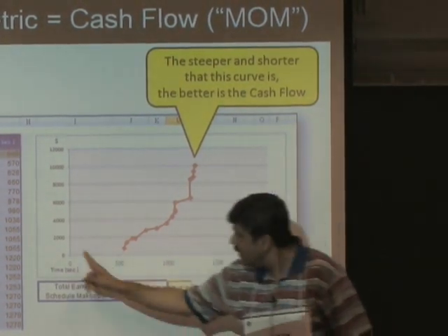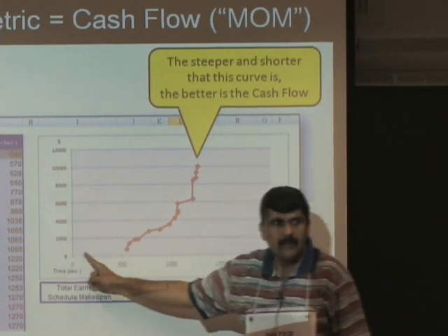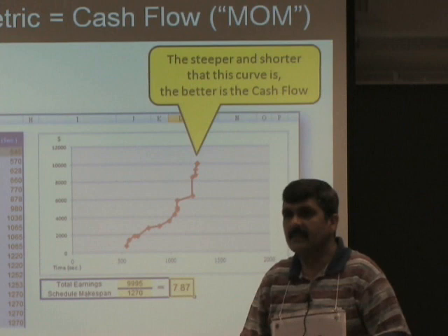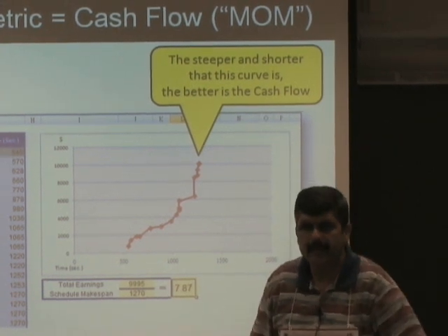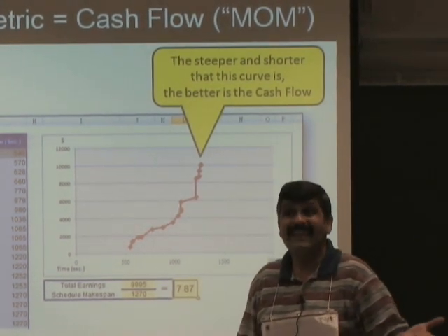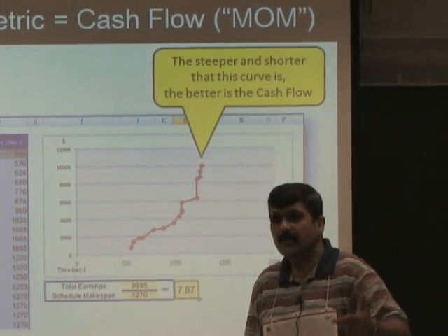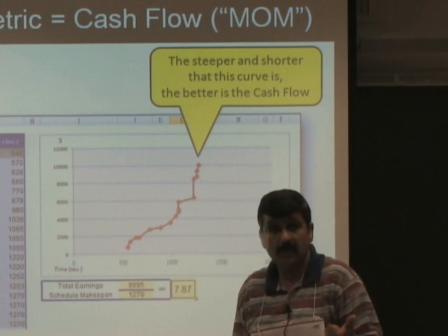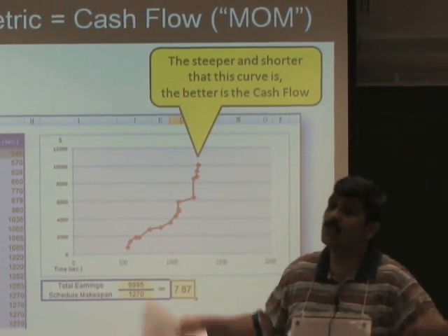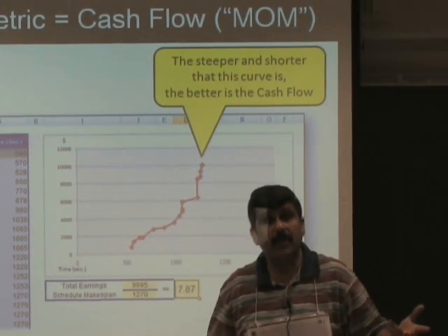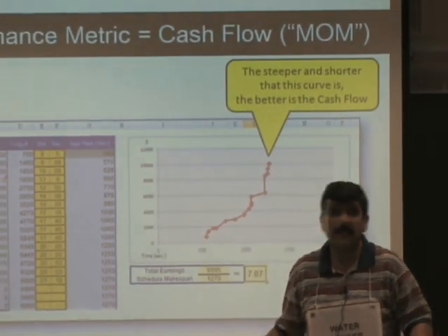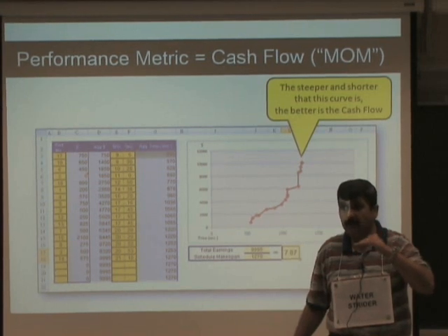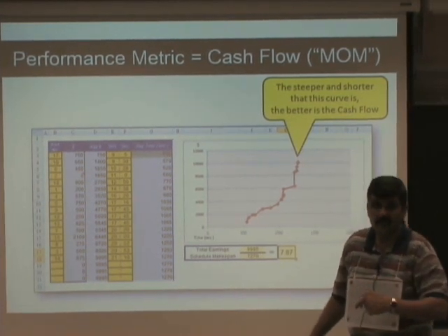So for example, you see this empty patch here? This is what a lot of companies do. They have no schedule and they follow the classic value stream mapping. Empty the queue at the end of the shift. Why? Because when the next shift starts, it starts cold. So at least maybe 30 minutes sometimes, there's no work in queue because the material handler has just come in. They are finding out from production scheduling in their production meeting what jobs need to be moved. Sometimes shops run empty for a period at the start of the shift and at the end of the shift.